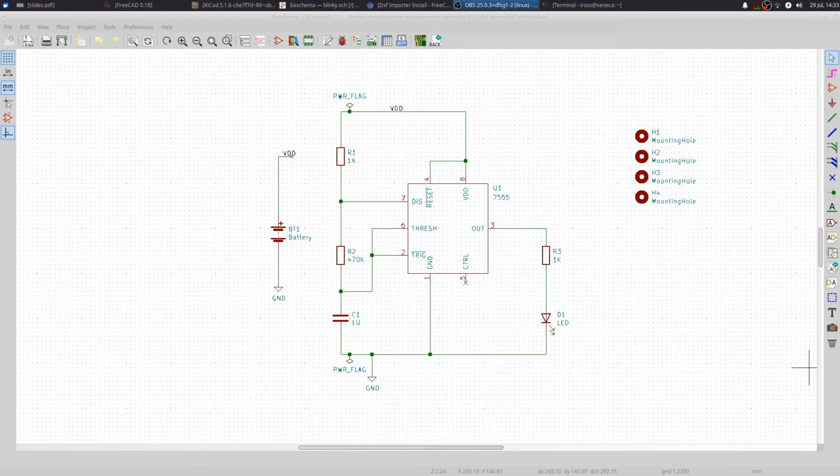So this thing I want to show you is a way to transfer mechanical and geometrical data from your mechanical CAD program, FreeCAD basically, to KiCad. And you can use this for PCB outlines and the position of mounting holes, and in our case for aligning the photo interrupter footprint with the motor encoder disk as precisely as we can.